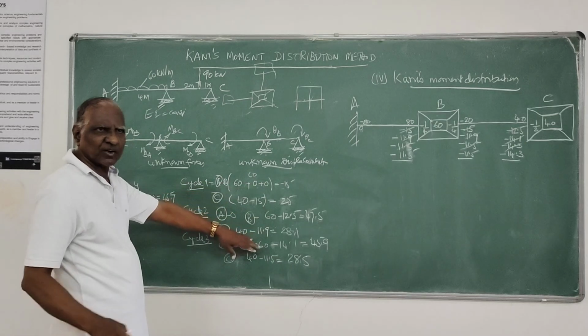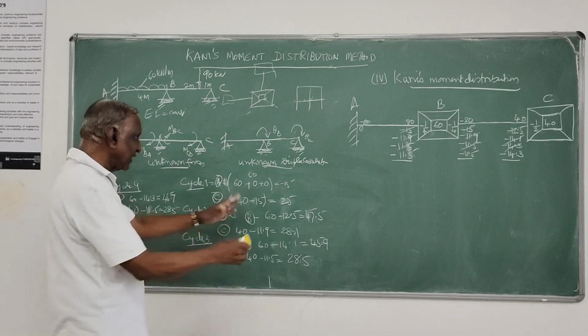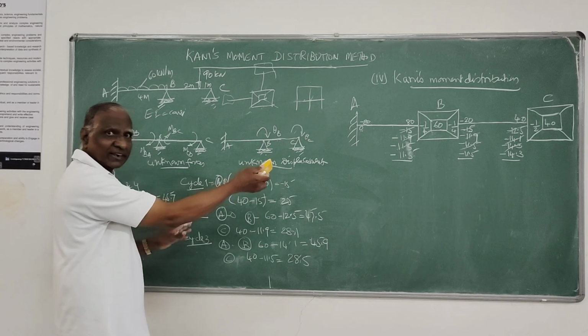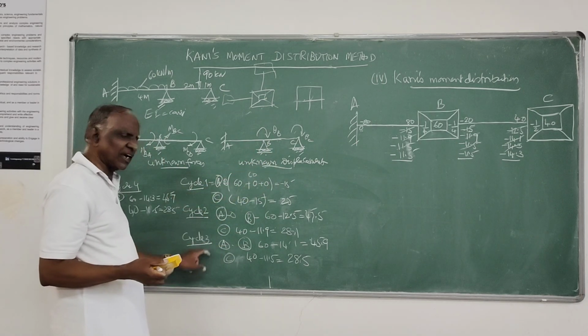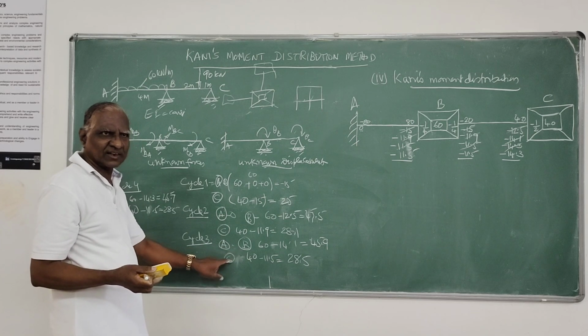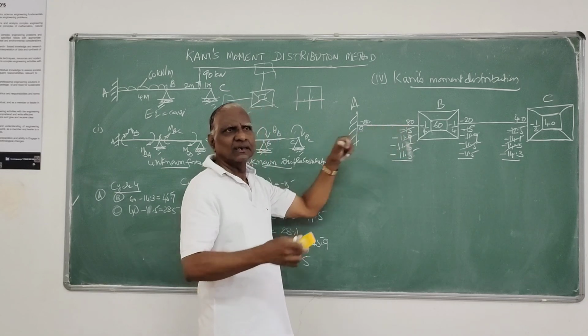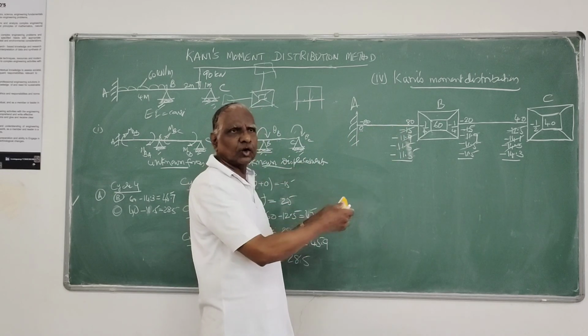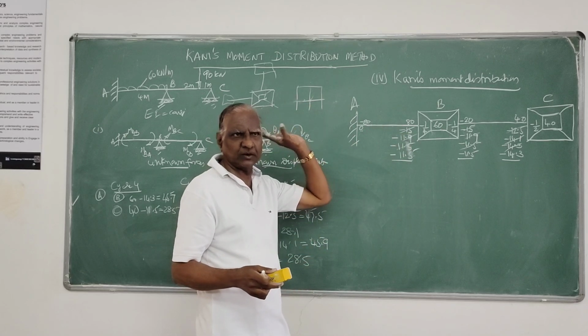This is only a rough kind of table I made. I told you we can do it on the right side, so that at any moment if you find some doubt, you have committed some mistake, you can verify here, where all calculations are there. Only the sum of the fixed end moments at each joint, the sum of the moment rotation contribution from the further end, and sway contribution. Of course, sway is not coming into the picture.